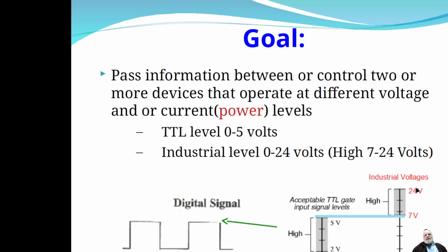However, if we look at something like a PLC, typically PLCs have digital inputs and digital outputs that are running at 24 volts DC. And so if you look at those, a low is still considered basically below 1 volt, or just call it 0.8 volts like the TTL logic. However, a 1 or a high doesn't really go active until you're at least 7 volts, or somewhere around 7 volts, which is well above anything a 5 volt controller can output, let alone something like a Raspberry Pi.